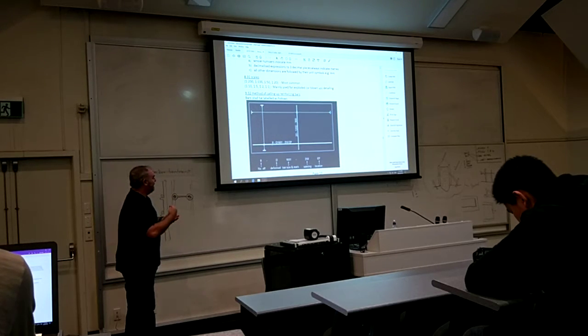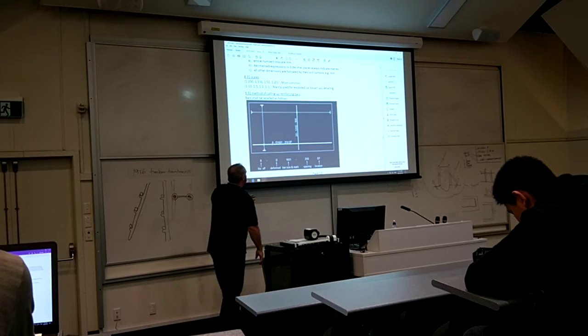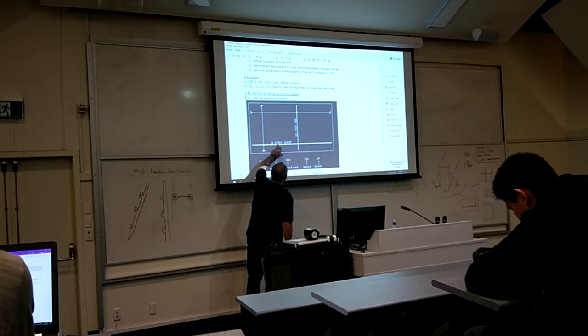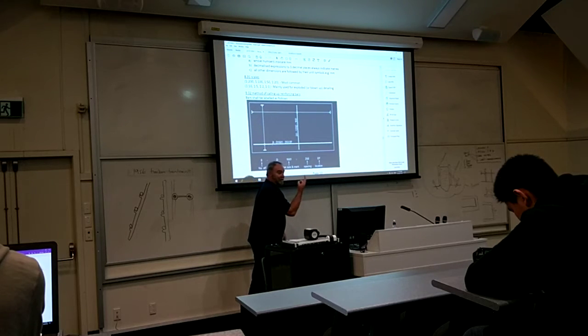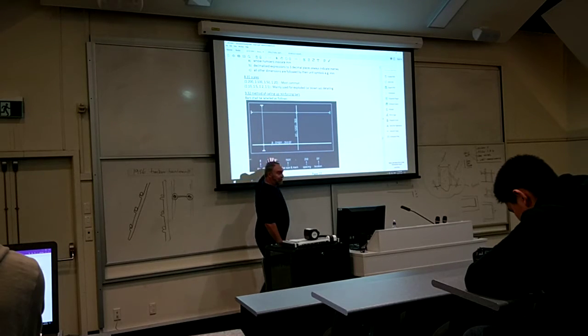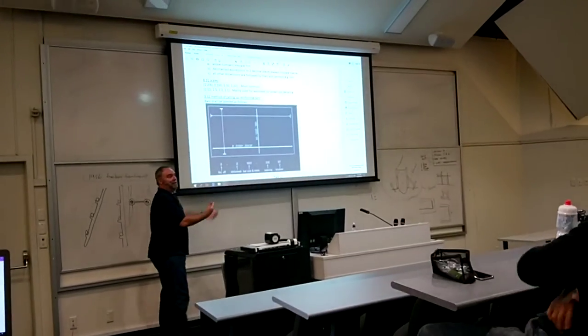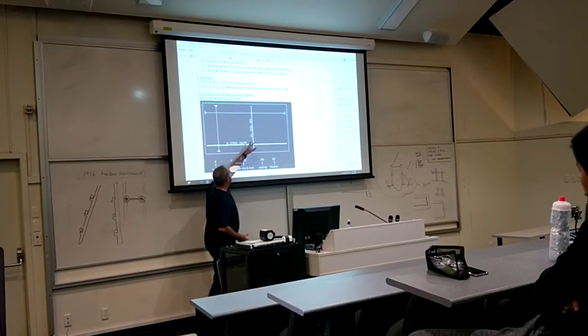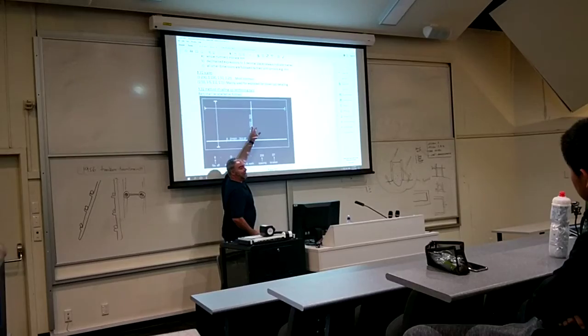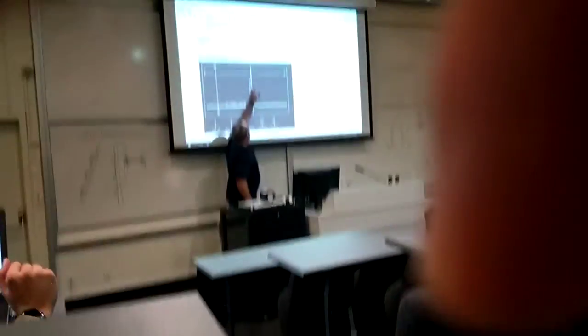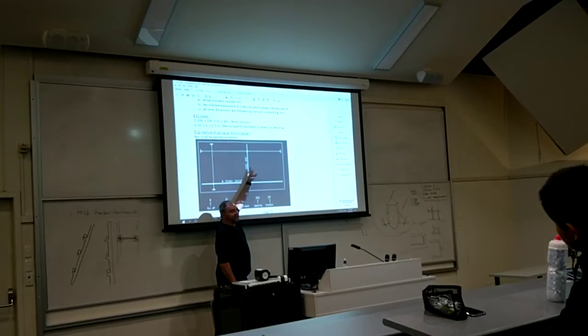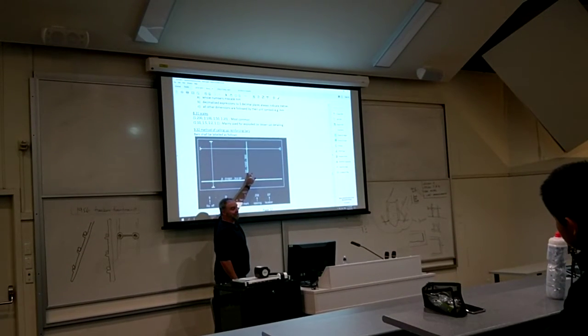So it's really important that you draw these things so that the steelfixer can understand it. It's dead right, and you don't get any of these numbers wrong. So that D stands for deformed. 16 is the diameter of the bar, and 01 is what we call the mark. A mark is just a label. So the next bar will be 02, there it is there. That one's a 12mm bar, it's not deformed. 02 is the mark, and that's at 300 spacings. And we've worked out that there's 20 of them.